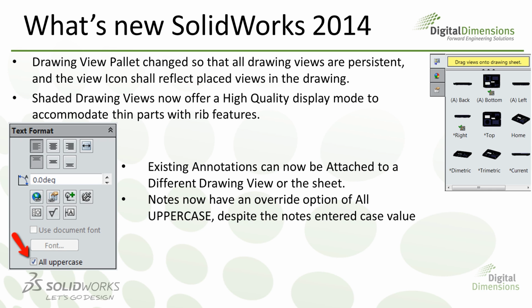Also, within a drawing, any notes that you have on your drawing can now be switched from one drawing view to another drawing view. So in other words, in the past, whatever view that you were closest to when you added a note, that's the view that it attached to. What's new for 2014 is that we'll be able to reattach that note to a different view.